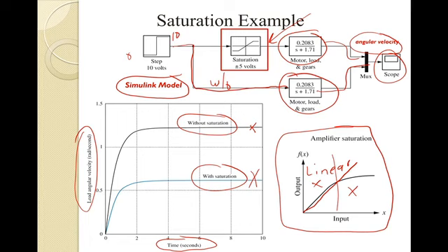In Simulink, they have a block literally called a saturation block, and we can go in and change the parameters, vary them, and look at the impact. So that's a saturation example.